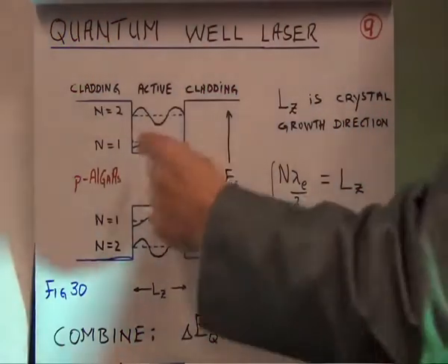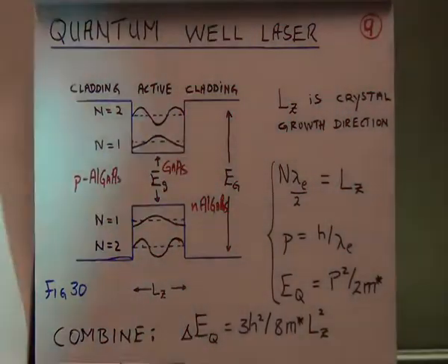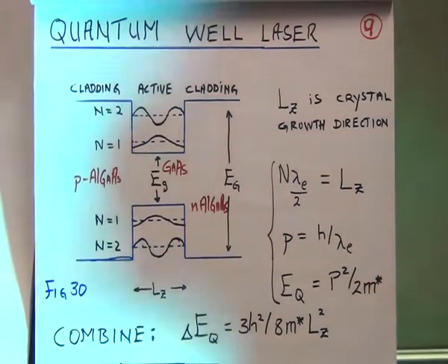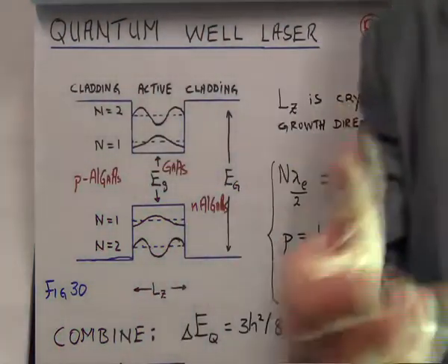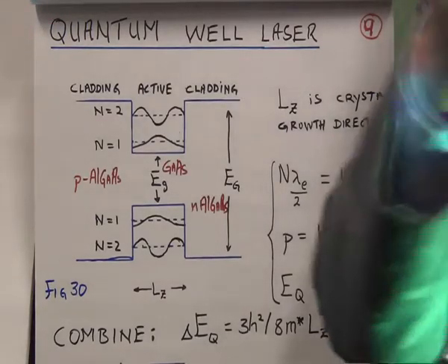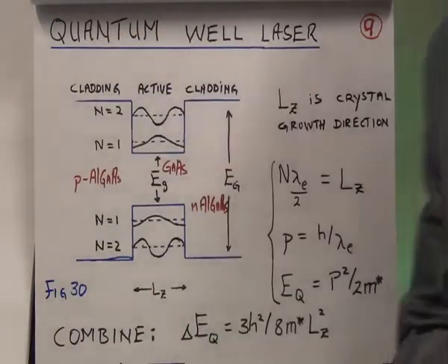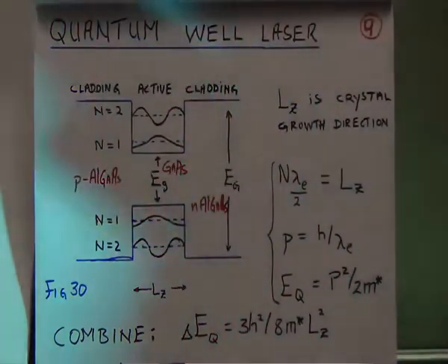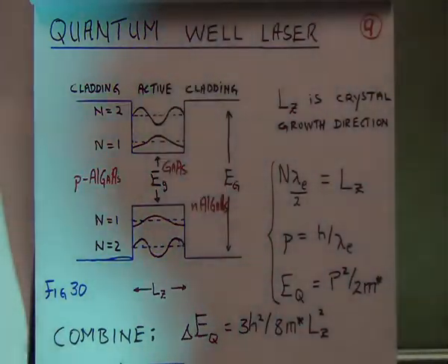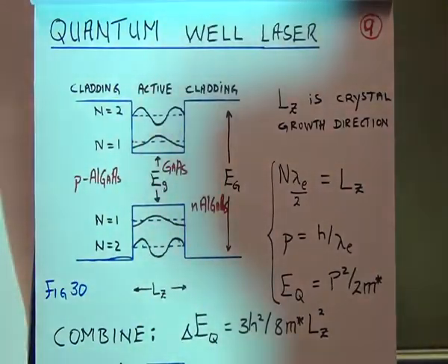And we're going to show that when the inner active nano layer of this laser is narrow enough, the threshold drops dramatically. And there are several reasons we need something like that. The higher the threshold, the more heating that takes place in the background in the chip. Heat degrades the behavior of the thing, and it broadens the spectrum. That adds to chromatic dispersion. All kinds of problems arise. Heat can also, as we've seen, kill the chip if there's a surge on top of this heating. So there's many, many reasons why we want a low threshold. Another one is for optical computers, which a lot of work is going on them today.